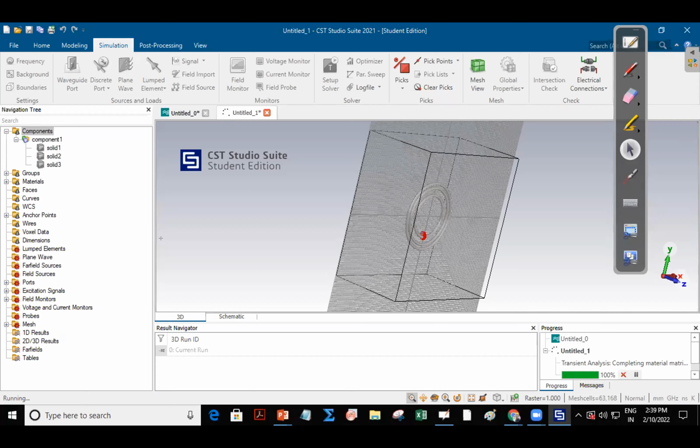Everyone make this project now of a loop antenna. We'll check the radiation patterns out of this. Loop antenna is a magnetic dipole, right? You'll find in the direction of maximum radiation, it will be opposite from the pole, what we have seen in the dipole before.